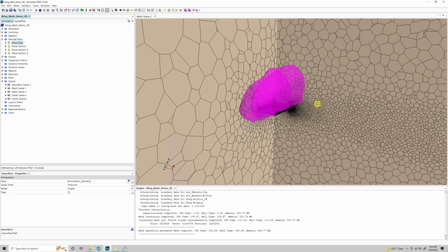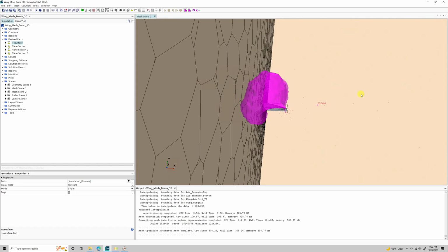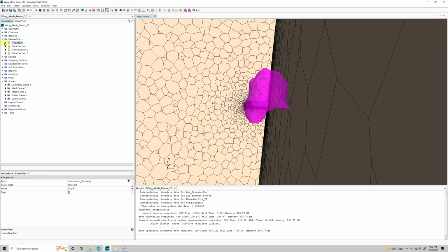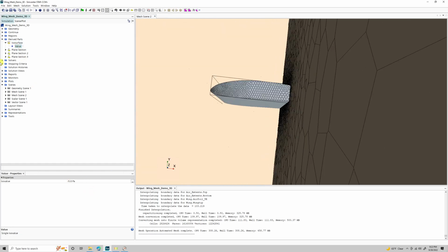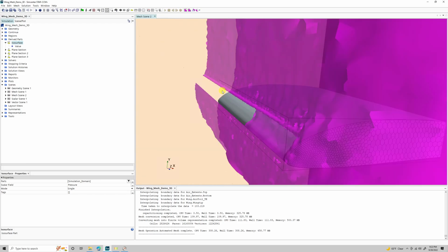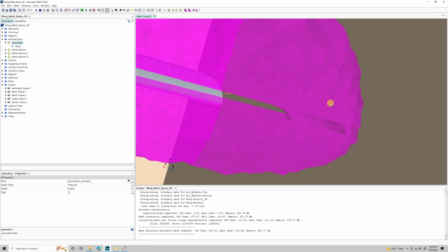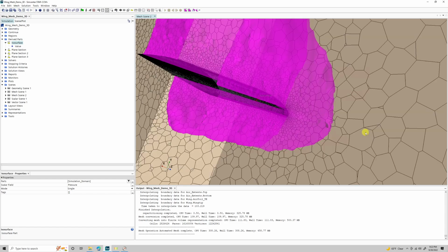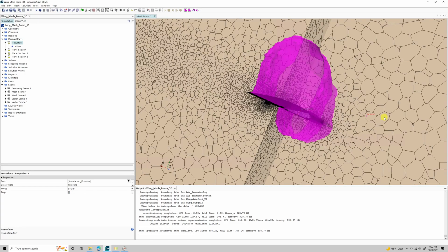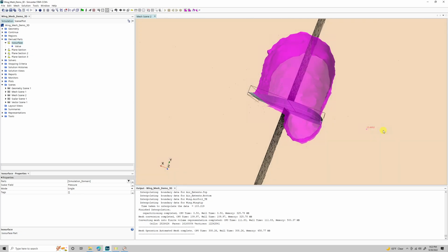So, there we go. I asked it to show me a surface in the simulation domain where pressure is a constant -5 pascals, 5 pascals below our reference value. And it's shown us. So there is this surface, and everywhere on this surface, which is mostly where we expect, right? We see that inside of this surface, the pressure is going to be above -5 pascal.